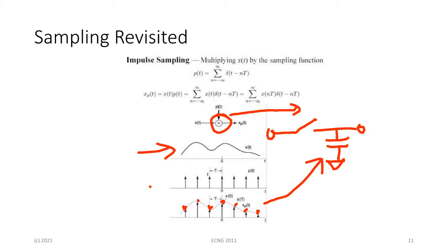In reality, what they would do, and you know of devices, electronic switches, for instance, a field effect transistor, right? Whether it's an N channel or P channel, if you bias it and turn it on, the channel conducts. You turn it off, the channel is an open circuit, high resistance. So you can use that as an electronic switch for argument's sake. All right. Remember, as I keep trying to stress, whatever we're doing here are models for whatever the real world is doing. So any questions on that?